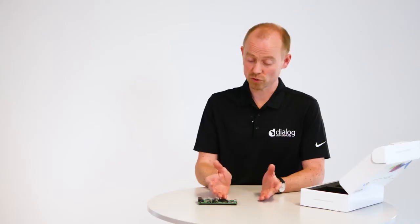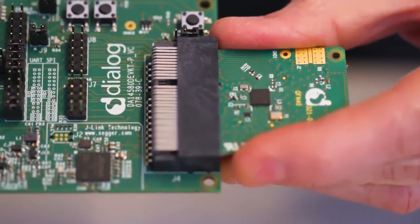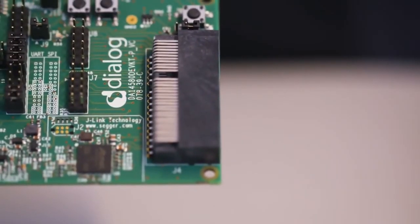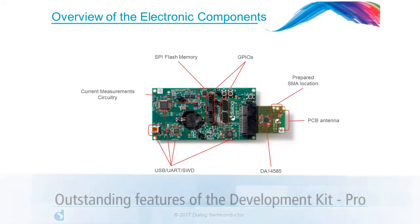For some designers, you may want to develop and test using the DA14586, which integrates 2 megabits of flash memory. To do this, the only thing you need to do is to swap out the DA14585 daughter board with the DA14586 daughter board.